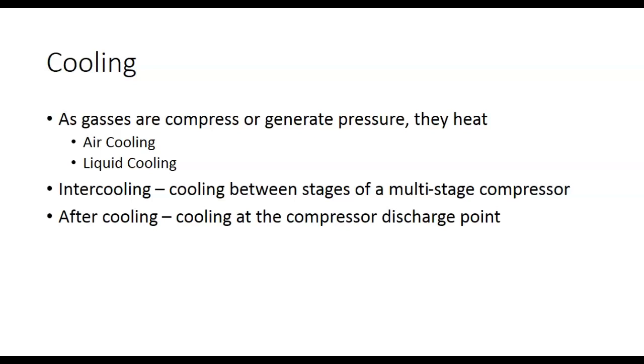And when you compress it, the cubic feet go down. So what's the moisture going to do? Yeah, it's going to release moisture. Plus, when you heat it up, and then all of a sudden you let it cool down, it's going to condense. So the big problem we have with compressors, whether you have one at home or not, is you're constantly fighting liquids, right? This one has an automatic drain on it, but somehow it's getting liquids into our lines. Some of y'all have had that happen, right? That's the biggest problem we have.